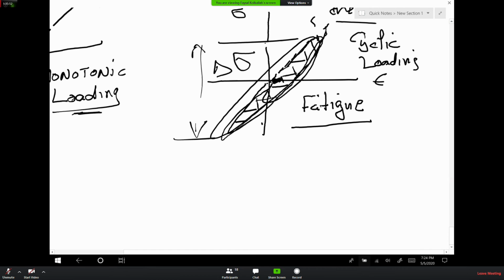Then the ship is sitting in the ocean water. That's salt. That's fine. The temperature of the ocean at night is cold, and in the morning, during the day, it's warm. That's fine. So where is the problem? There was a crack somewhere on the ship. There is a flaw, a crack. And due to the salt water, there is corrosion. Due to the change in the temperature, there is thermal fatigue, delta T.